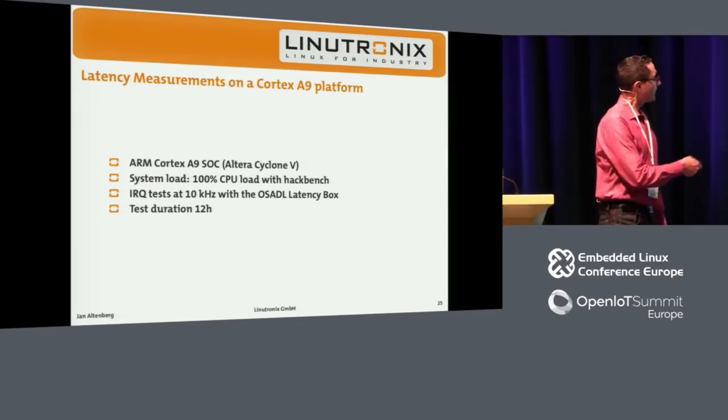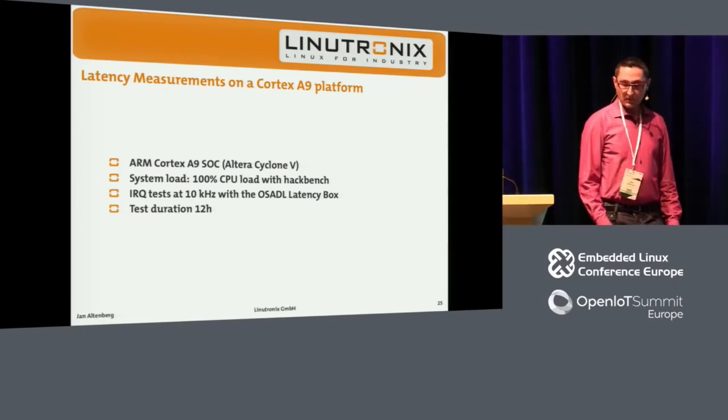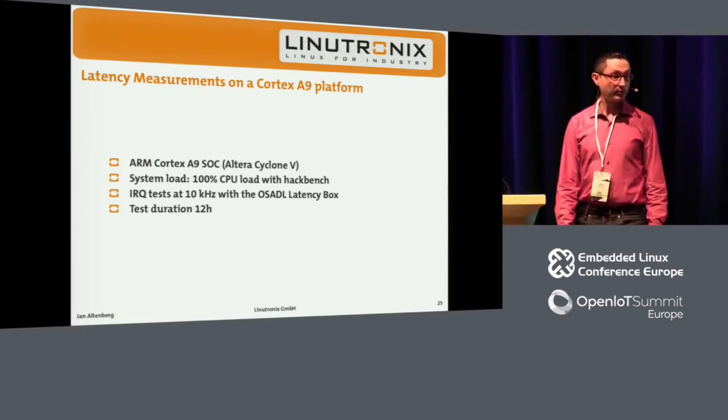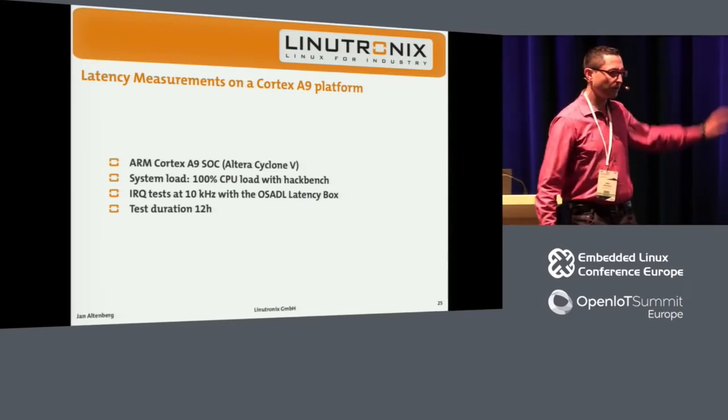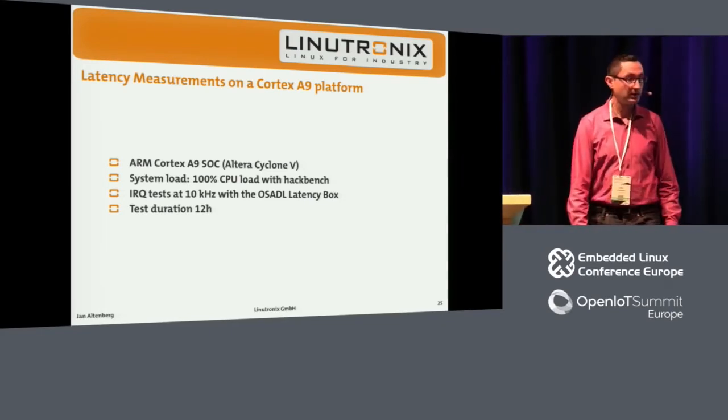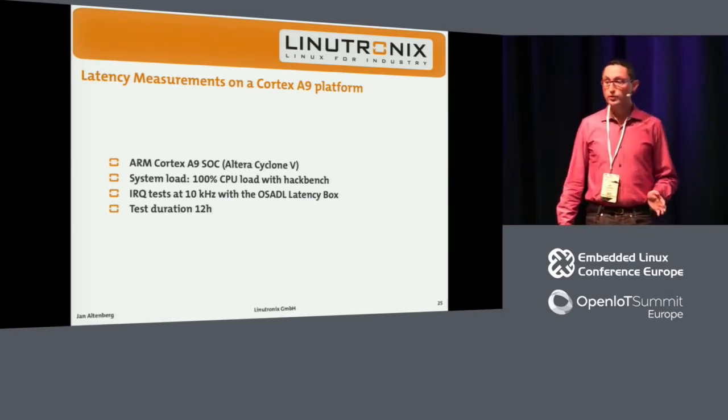What we did was IRQ tests. We fired IRQs with a frequency of 10 kilohertz. We took the OSADL latency box to do that. I will tell you how this box works later on. And we put the system in a worst-case scenario.